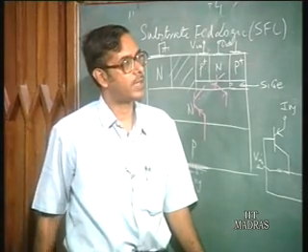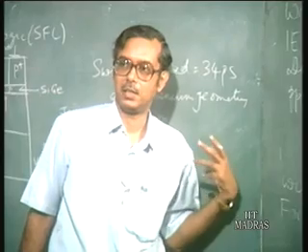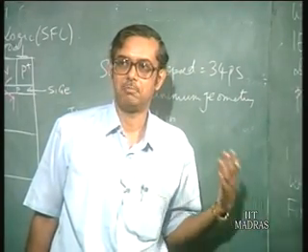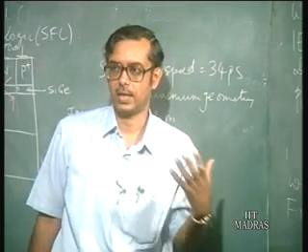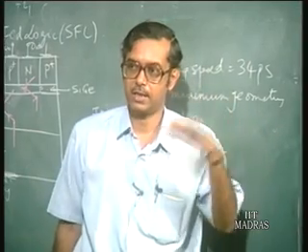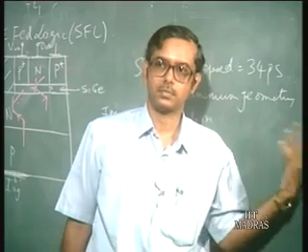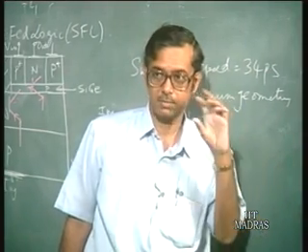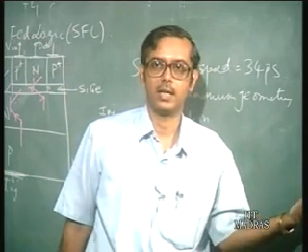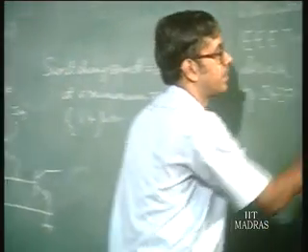With that, I think we come to the end of this discussion on high speed, the different efforts going on to make I²L a high speed family. From the technology side, we have seen how self aligned technology improves the speed and reduces the delays, and then there are circuit modifications like the Schottky transistor logic, as well as these heterojunction I²L concepts.